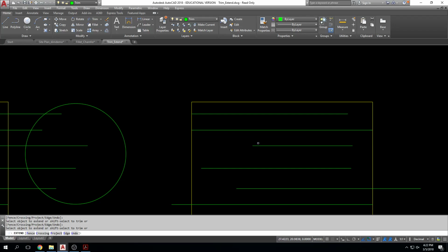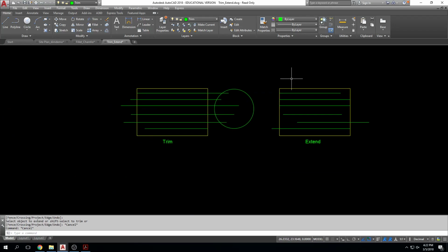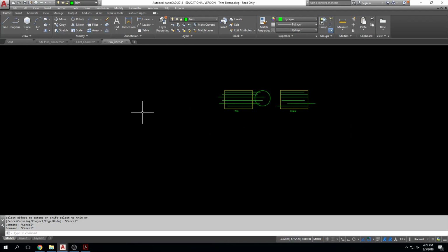So click, click, click, click. There you go. Okay. Again, trim and extend modification commands are really great for cleaning up geometry, right? They're commands that I use all the time when I'm drafting in AutoCAD, but I would say that by and far, I end up using fillet a lot more because fillet will trim and extend depending on the condition I'm using it on, right? So that example I drew over here that's gone now because I undid it, fillet will just sense what needs to happen. That's why I like it, okay?